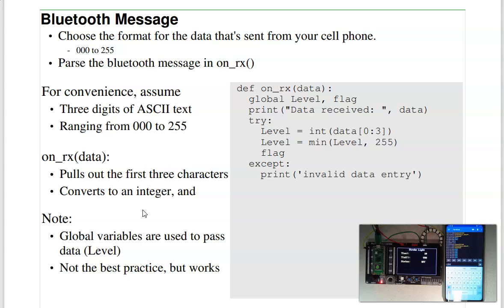So when I do that, I've got to send a message, and this is really up to you, the programmer. What does the format of the message look like? Now, I used to work with a company that had a mandate back in 2000. They required all messages to be in ASCII. It's not quite as efficient, but the problem with binary data is that if you lose the instruction manual, you have no idea what's going on. At least in ASCII, you've got a shot. And if the programmer is really nice, they'll set it up so if I send something like help or question mark, you'll get back the instruction manual for that eventual day when you lose the instruction manual.